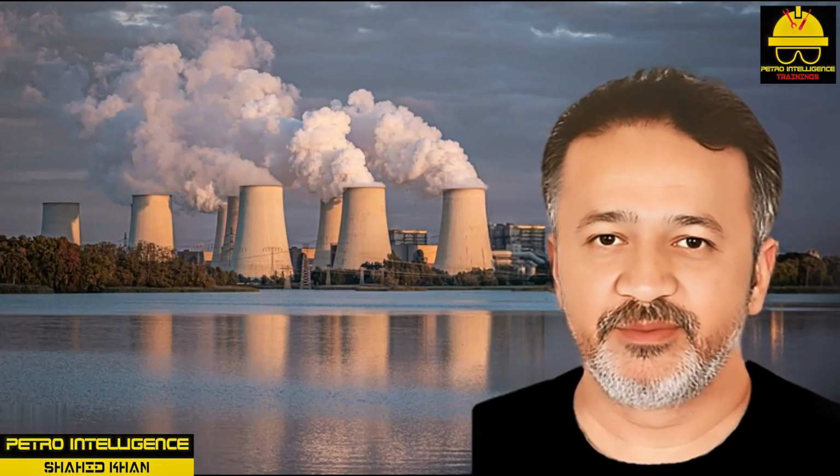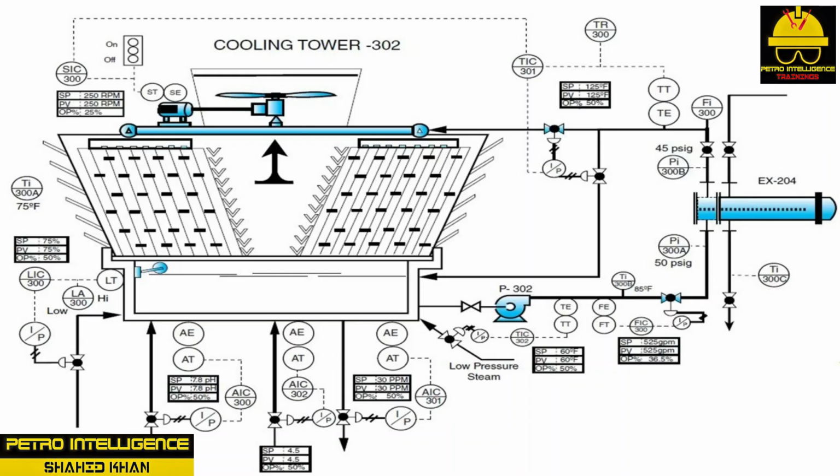Cooling tower system. Cooling tower 302 is classified as an induced draft, or draw-through, cross-flow, single-cell device that is primarily designed to control the temperature on condenser X204. A cooling tower is often referred to as a heat rejection device designed to extract excess heat from the returning water and expel it into the atmosphere. This picture shows what the cooling tower system looks like.